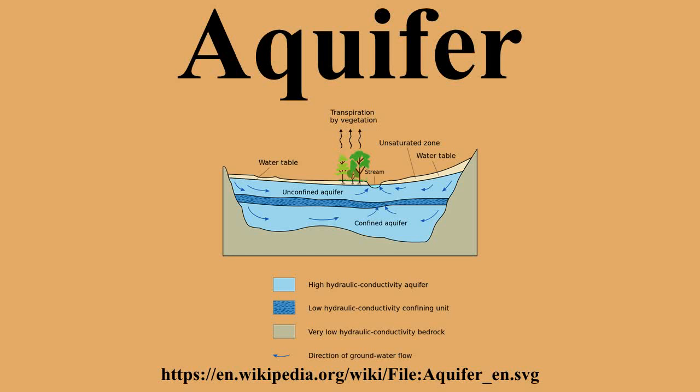Semi-confined aquifers with one or more aquitards work as an anisotropic system, even when the separate layers are isotropic, because the compound KH and KV values are different. When calculating flow to drains or flow to wells in an aquifer, the anisotropy is to be taken into account, lest the resulting design of the drainage system may be faulty.